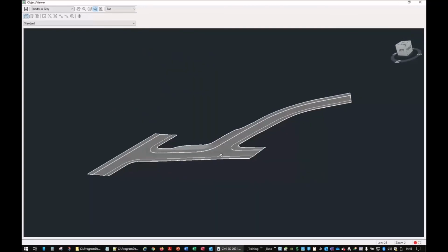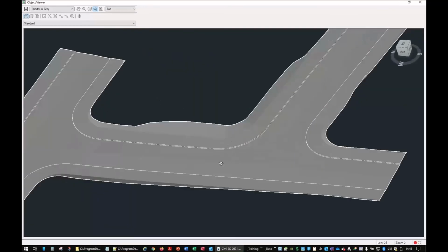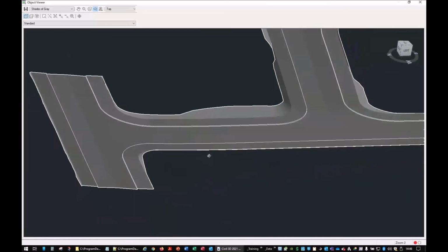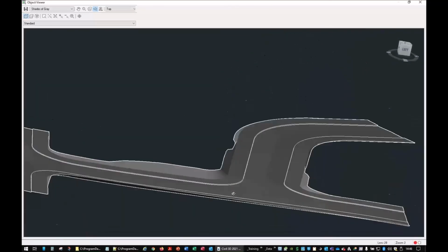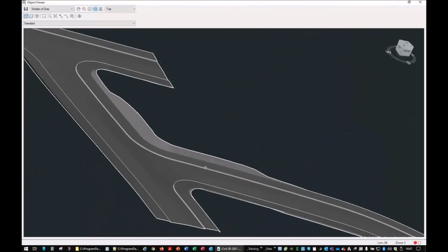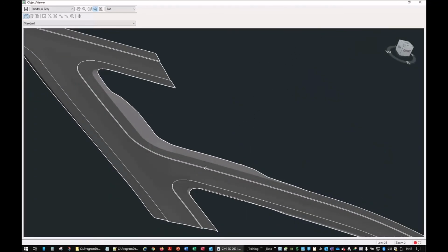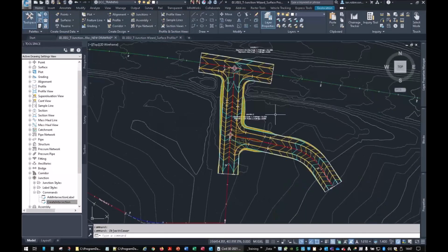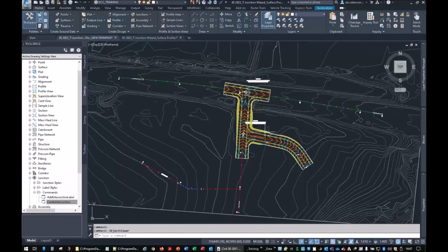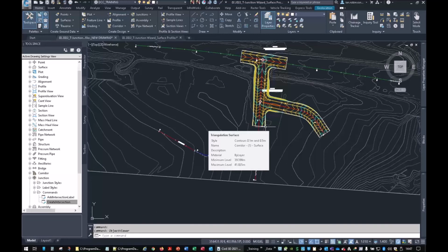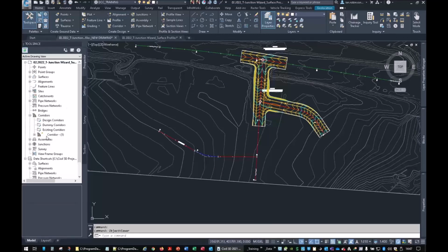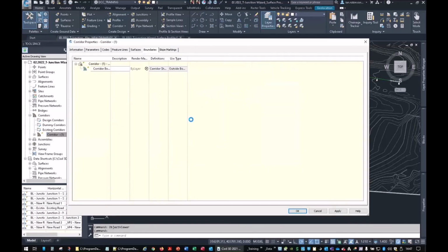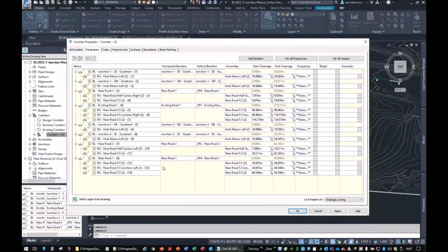Look at that. Beautiful. All the crowns tying in, all the curbs tying in. So essentially, when you understand what the wizard's doing, and you've set it up how you want to do it, if you're doing housing estates and stuff like that, dead easy. Just bang them in. But just bear in mind, you're making a lot of data. You know, even that tiny corridor there, we've created quite a lot of data already.